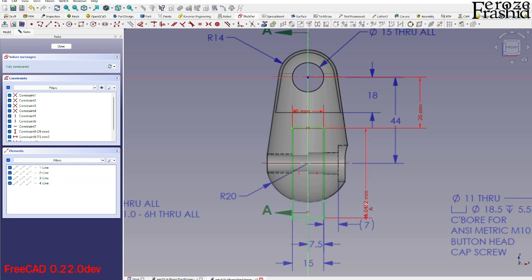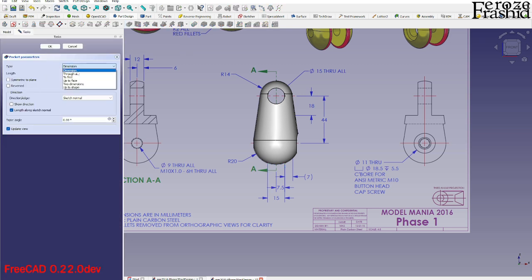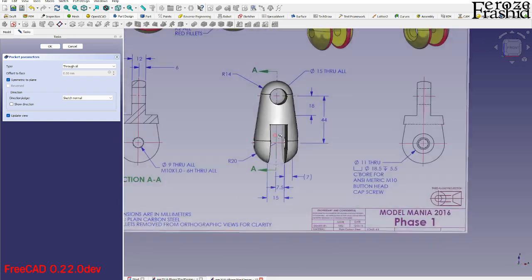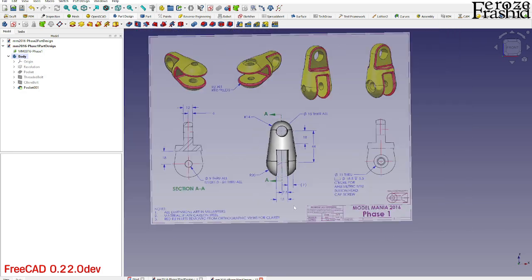The only thing left is this dimension, which is, we can go as far as, as long as it is past this point, we are fine. Okay, so this is the sketch bottom cut. And I want to make a pocket through all and symmetric to the plane. So that makes it a pocket through all, symmetric to the plane. Okay, now let's take care of this top cut.